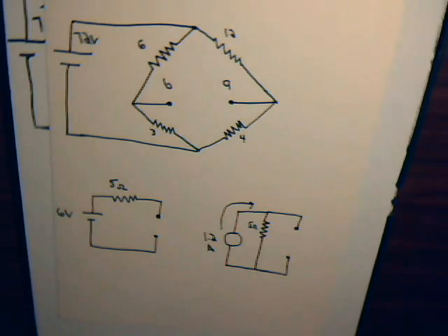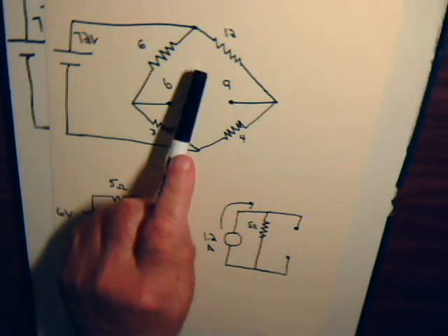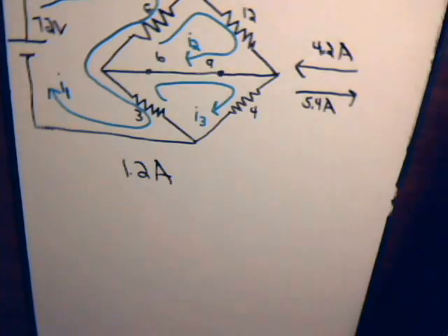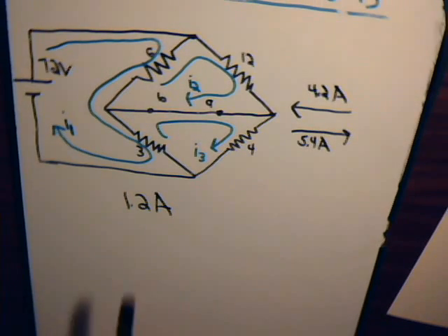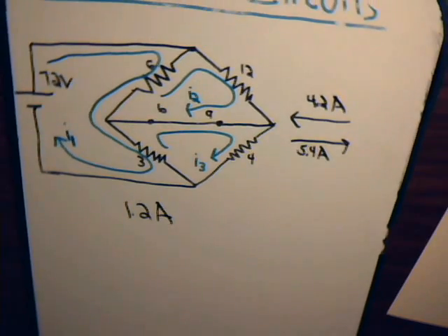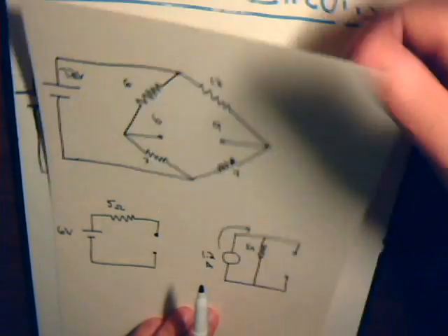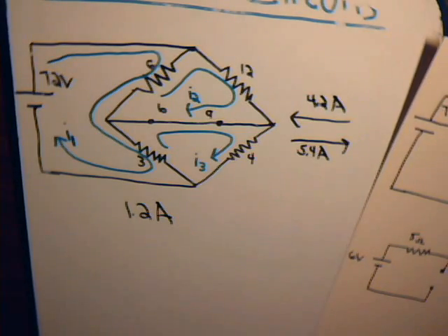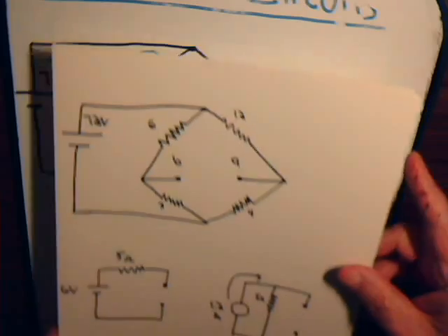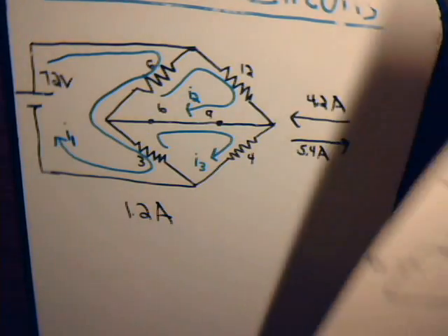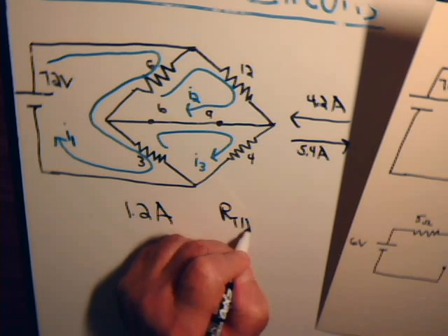And actually that's the smarter way to do the problem, because to go from here to here is pretty short, to go from here and determine the Norton equivalent current. As you saw, it took a bit of work because we had to deal with 3 separate loop equations. But if we started the problem from here, then we'd say, all right, we know what this is, and as you saw us do in the previous video, we're not going to repeat it, to determine the Norton